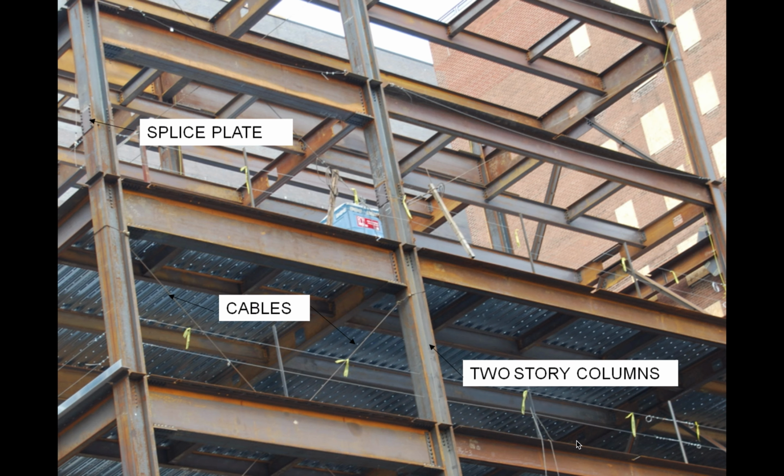Okay, here's another couple of terms. You've got those turnbuckles or cables. Many columns are built to span 2 stories, so that all you have to do is make connections, and there's less splicing that you have to do. The reason why we usually go with a 2-story column is that's probably a 20 to 30 foot piece, which is just good for 2 stories of a building.